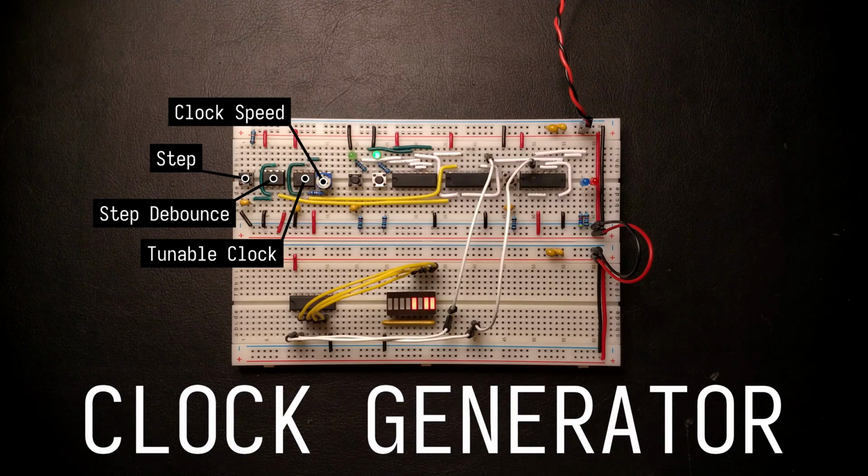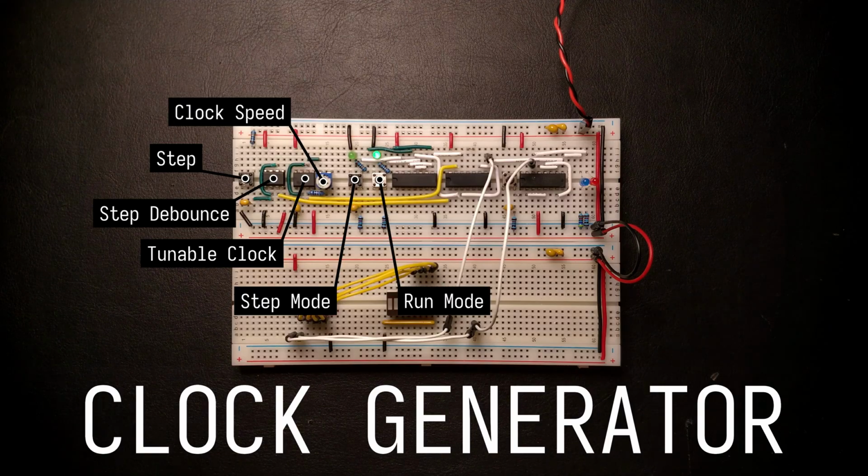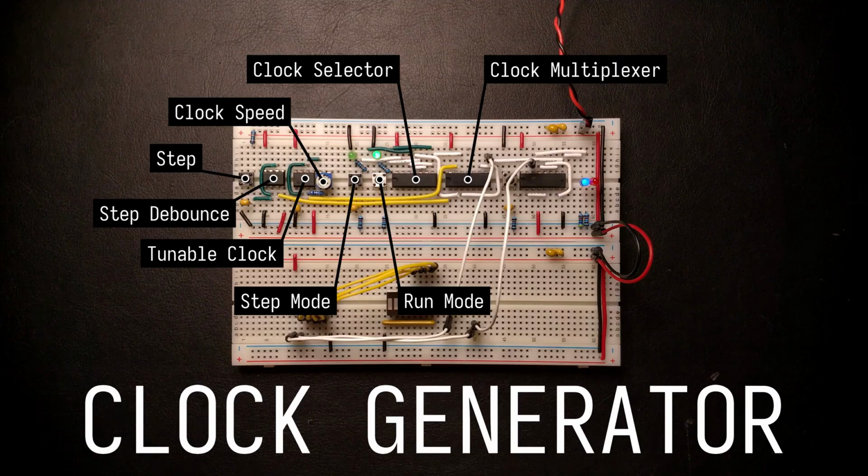Next to these clock sources, we have the selector buttons, which allow me to either put the clock generator into step mode, where the clock essentially halts and waits to be triggered through the step button, and the run mode, where the tunable clock takes over. We've used 2 NAND gates to implement the clock selector, which is essentially just an SR latch that keeps track of which mode is active. Then we've used 3 NAND gates to build a clock multiplexer, which feeds either the single stepping or the free running clock through to an output pin, based on the output of the clock selector.